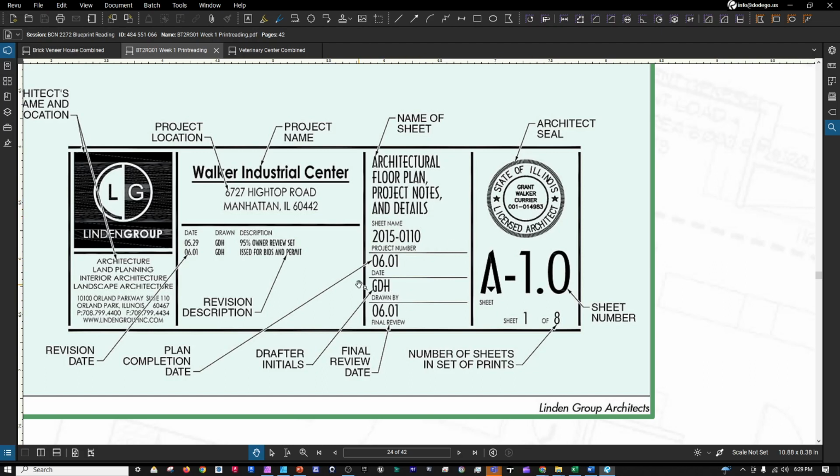So it's typical to have a drafter actually draw the drawing of the building and then the architect in that firm who's licensed will review what was drawn, make sure everything's up to code and standards, and then once we're ready, stamp the drawings and send them out to the general contractor to have it bid out, and also to the city, whatever the project is at, the AHJ, the authority having jurisdiction, to submit for permit. All right. A lot can change even after this is issued.